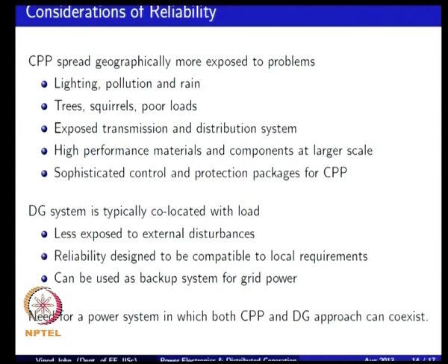So, if you are looking at the actual load connection to the physical distribution system, it is a very large number. So, even if a load has a failure of once in 5 years, if you have many thousands of loads, these faults are occurring all the time, and you need to be able to deal with that, especially when it is spread out in a large geographical manner.